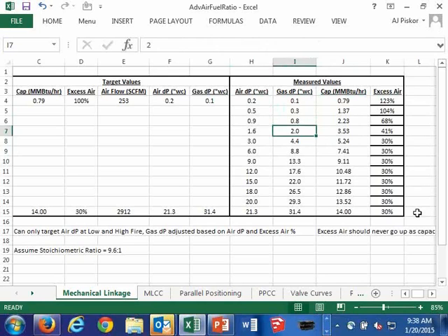But it's not necessarily such a bad thing to have excess air at the low end. In this emissions-driven application, usually the way that these are drafted up, you need to show that you are efficient over maybe a 4-to-1 turndown. So we're only looking at above index 2 or index 3. And the other good thing is that even though maybe we're not as efficient from a fuel standpoint, we're able to drive the combustion chamber down to a lower temperature with additional excess air. And really, when your burner's at low fire, that's what you want. You want to drive your temperature down on your chamber.